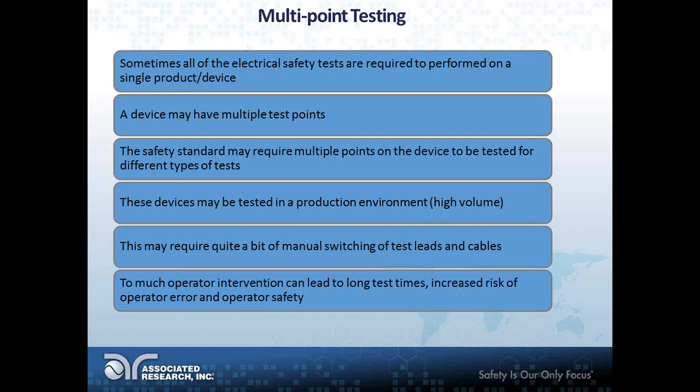As we know, recent advances in electrical safety testing technology have made complying with safety agency standards far easier and more efficient for electrical product manufacturers. From appliances to medical devices, most electrically powered products must comply with safety standards that specify some combination of Hipot, ground bond, insulation resistance, and touch current tests.